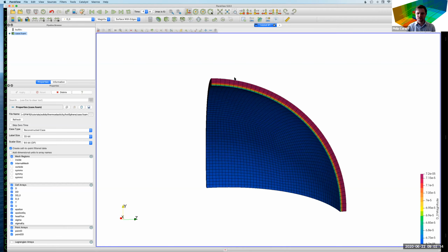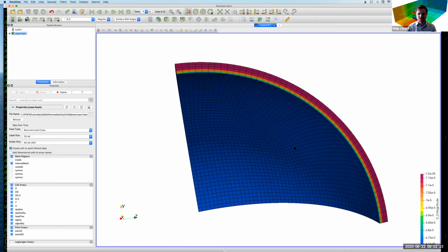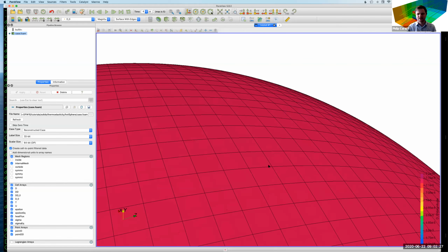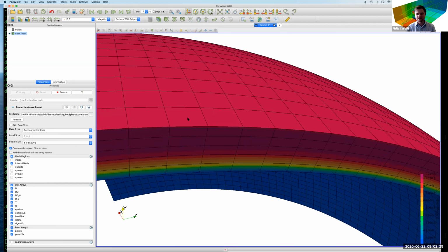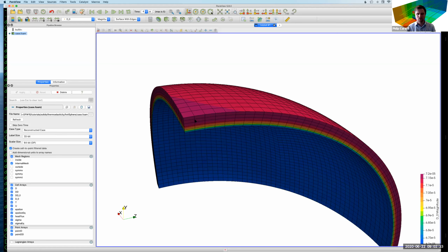If it's small strain, it means if I take one cell, and the deformation is a small fraction of the size of the cell, then you can ignore the effect it has on the movement of the mesh. So you solve for a displacement field on top of a stationary mesh, because the changes in volumes and areas of the mesh are so negligible, it's fine to ignore. That's called a small strain assumption.